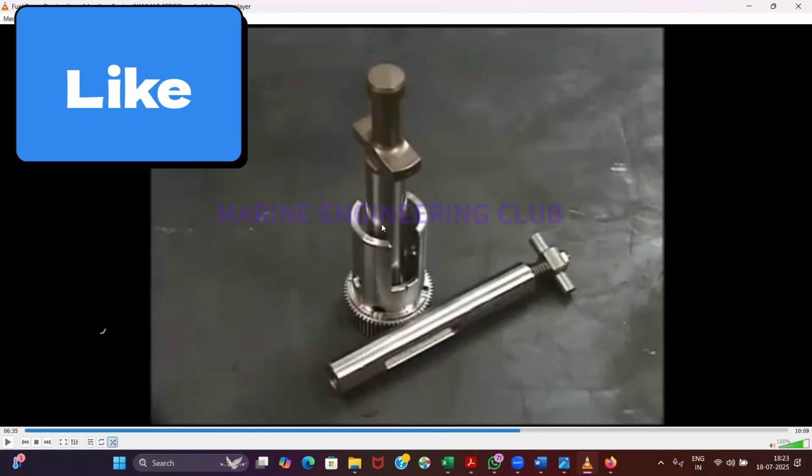Okay. So see, whenever you have to box back your fuel pump, the only markings apart from the pin in your plunger, which you mark and align on the body, are these: you have to align your plunger foot marking, control sleeve marking, and your fuel rack marking.